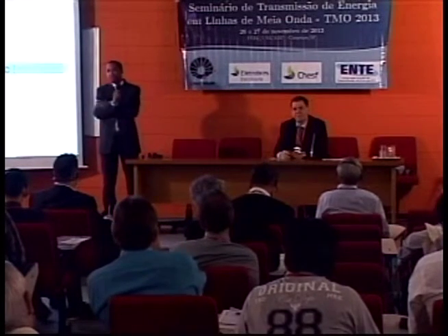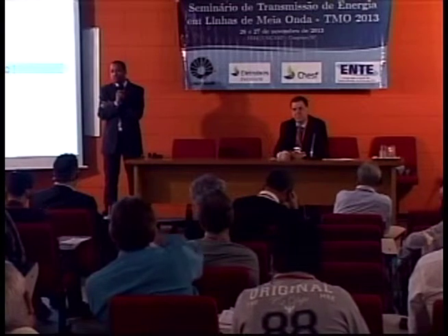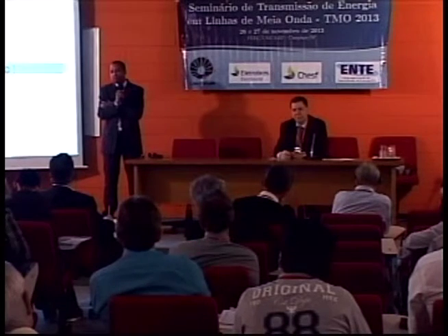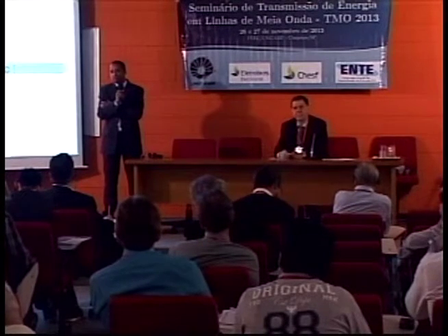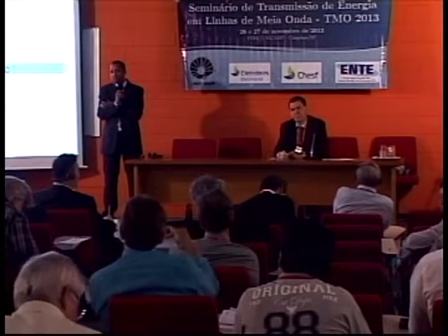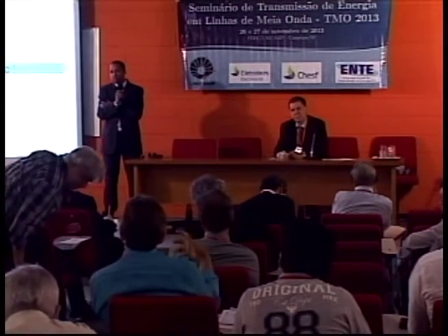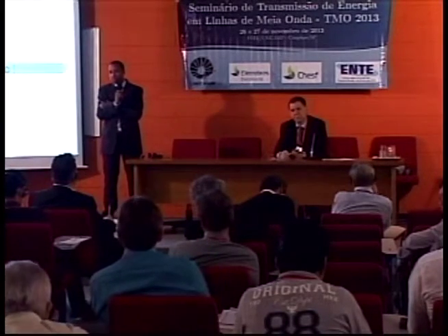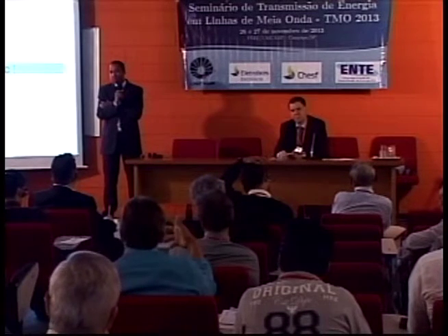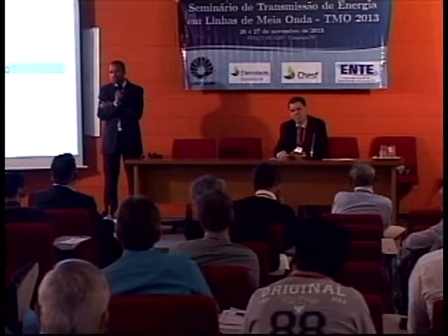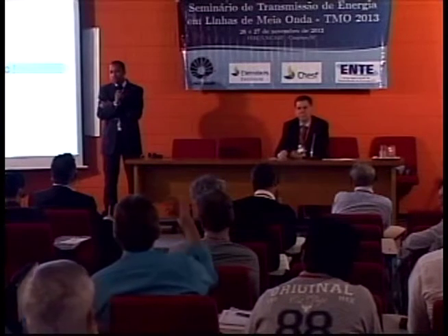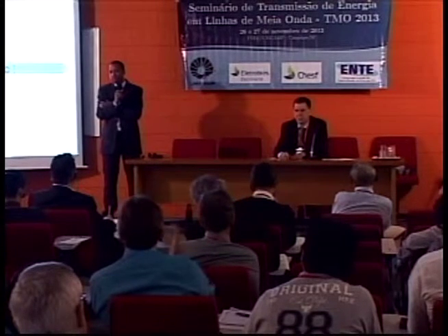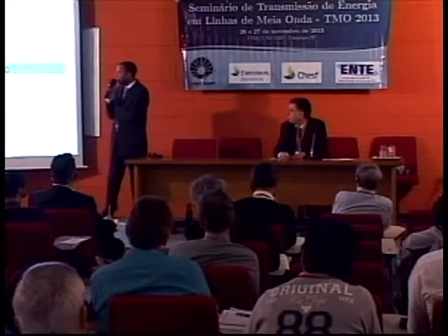Because what I understand is the substation, the bus bar arrangement in the substation has physical distances. And the substation itself has its natural frequencies of oscillation. And this kilometric distance must be chosen in a way that the natural frequency for this segment you are assigning as a kilometric distance reflects frequencies with the same values in the bus bar arrangement in the substation that would characterize a more critical situation. But you're not representing the detail of the bus bar in the substation. Could you comment on that, please?